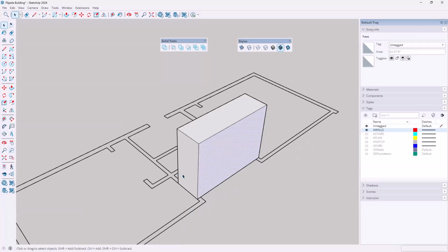And before I make a solid, right now it's lining up right here with this edge. I want to bring it in. And you'll see why when I start to use my solid. So I'm going to type P for push pull. Sorry, and it's already highlighting that surface. Let me go ahead and tap my escape key and then click on this surface.